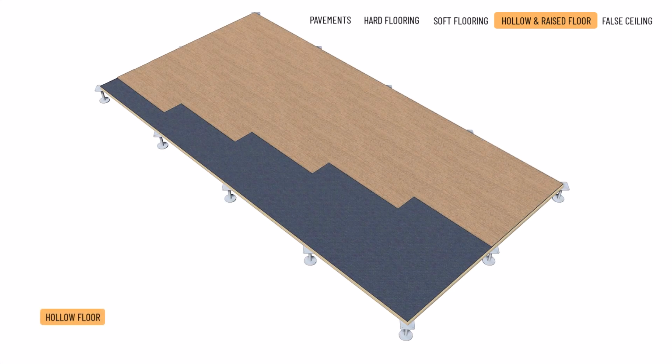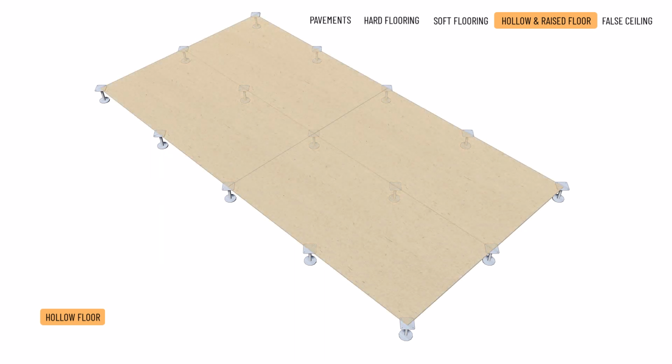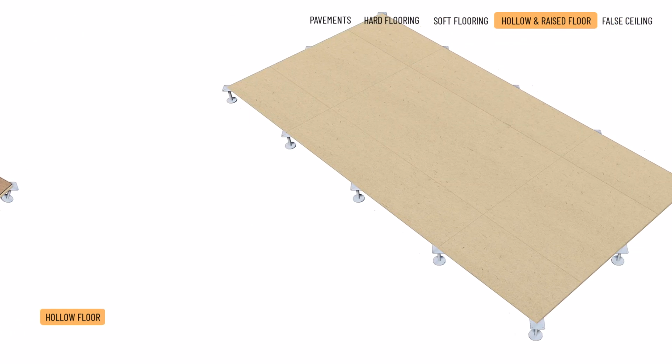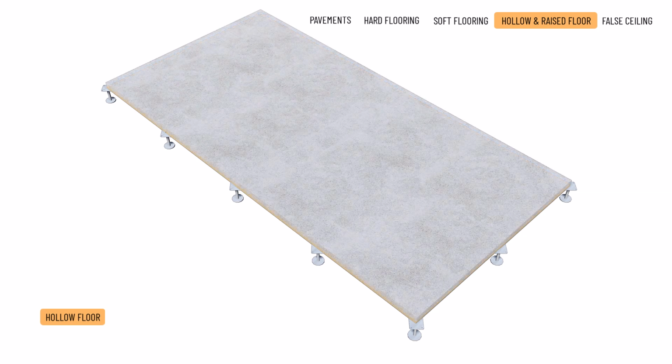Hollow floors and raised floors. Hollow floors are shell structures built on adjustable pedestals with heights ranging from 20 to 220 millimeters, forming the flooring subfloor. For soft flooring types, the floor finish is applied directly onto the gypsum or gypsum fibre construction boards of the shell. For hard flooring solutions, a gypsum screed is first installed on a PE separation foil.